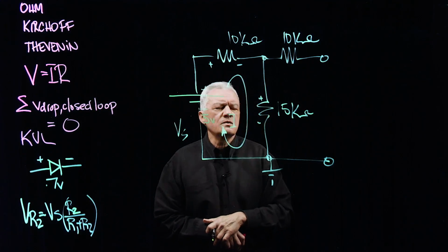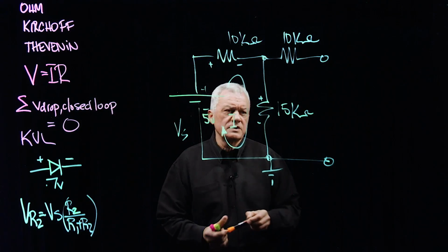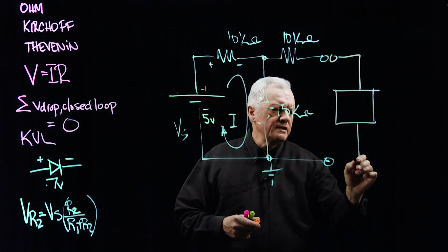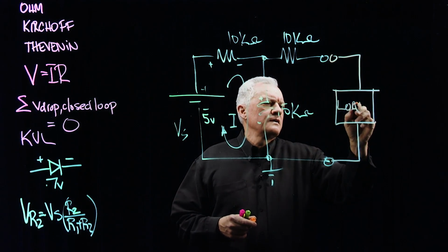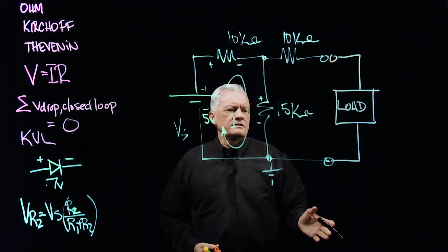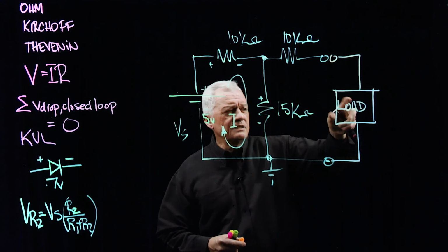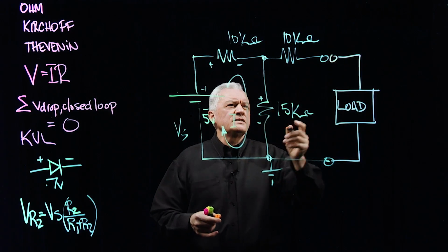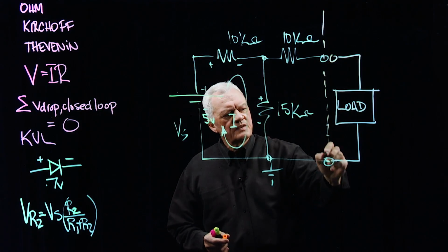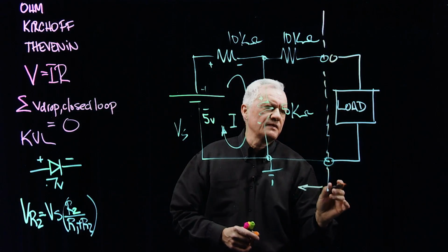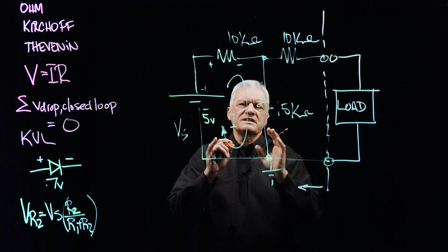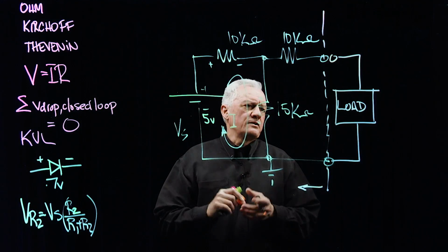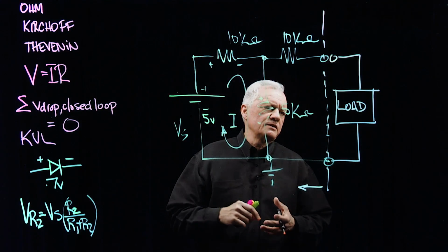All right, so what we do is, in our circuits, we tend to apply a load. And a load is just something that requires current, okay, a load. And these loads can be different. I mean, if it's some kind of a heating device and you keep turning the thermostat, you're going to draw more or less current. So the thing is, what we'd like to know is, really, if this is a black box on this side here, regardless of the load that's applied, at least let me understand what's coming out of my black box. What is the voltage? And what is the internal resistance, which then would drop the voltage as current is pulled.